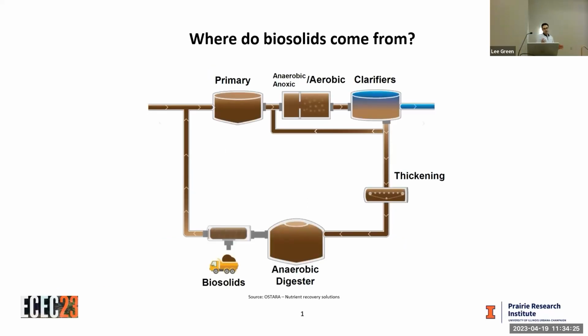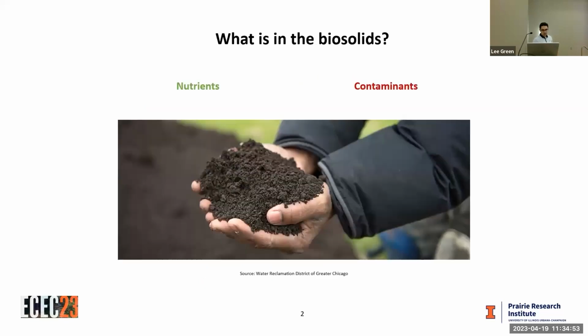Okay, so biosolids come from wastewater treatment plants. These plants receive residential wastewater, industrial wastewater, and also landfill leachates. Since the 1990s, all landfills are required to collect the liquid waste and send it also to the wastewater treatment plants. They treat all these kinds of waste, and then the solid residue is what we know as biosolids. These biosolids are very rich in nutrients and minerals, so they are a good soil amendment.